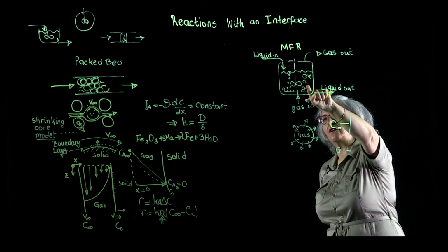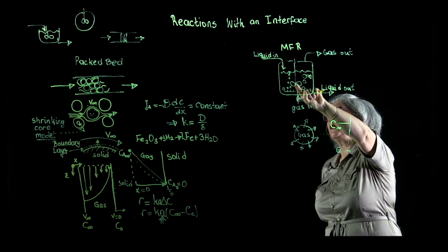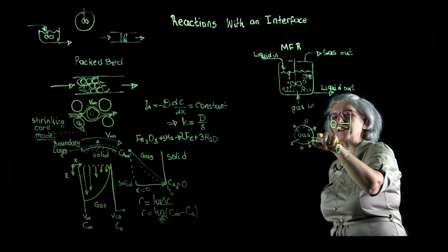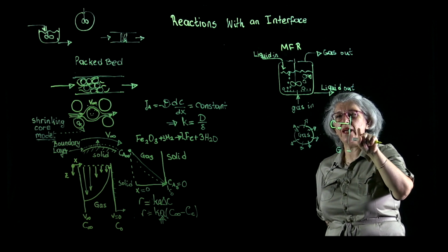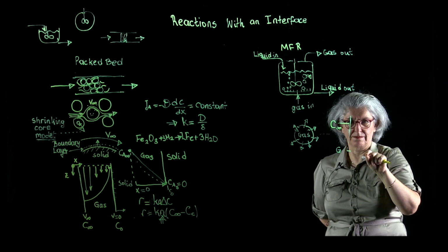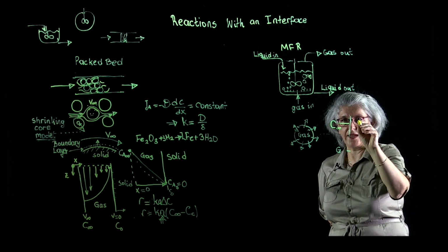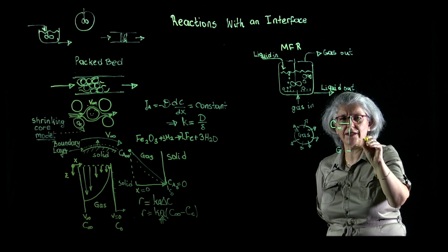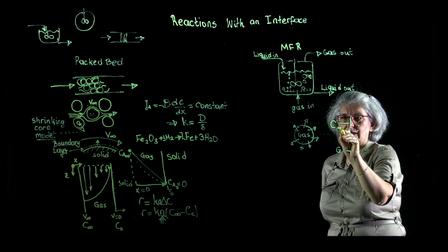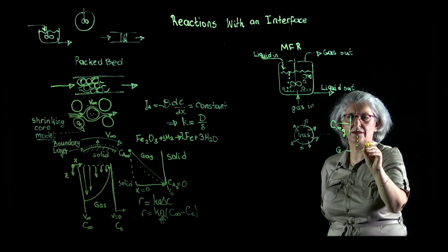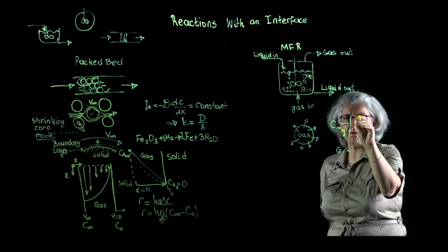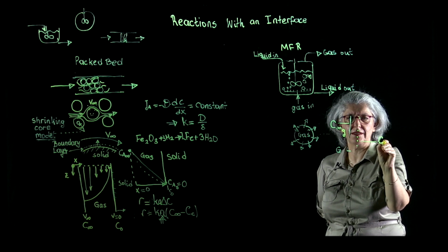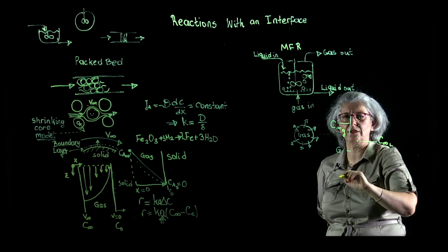It's going to be uniform across the interface. But when we have a liquid which is being stirred by an impeller around this gas bubble, we will have some domain that is not going to behave like bulk, but beyond that we will have C infinity liquid.